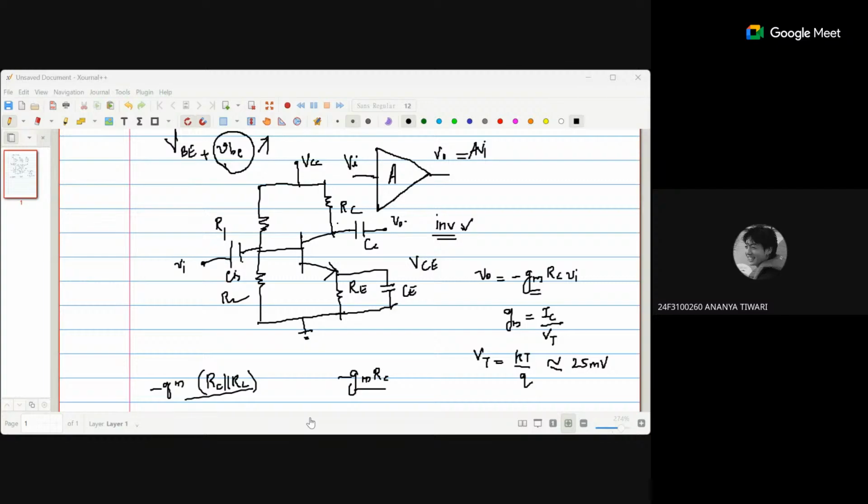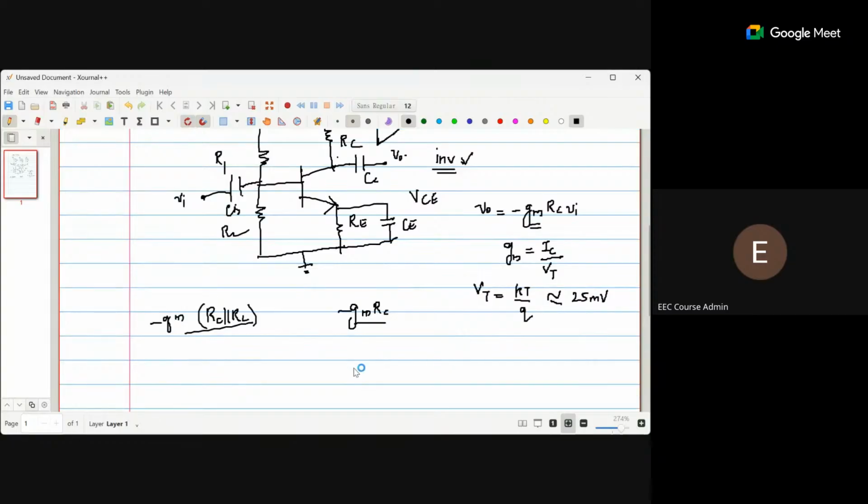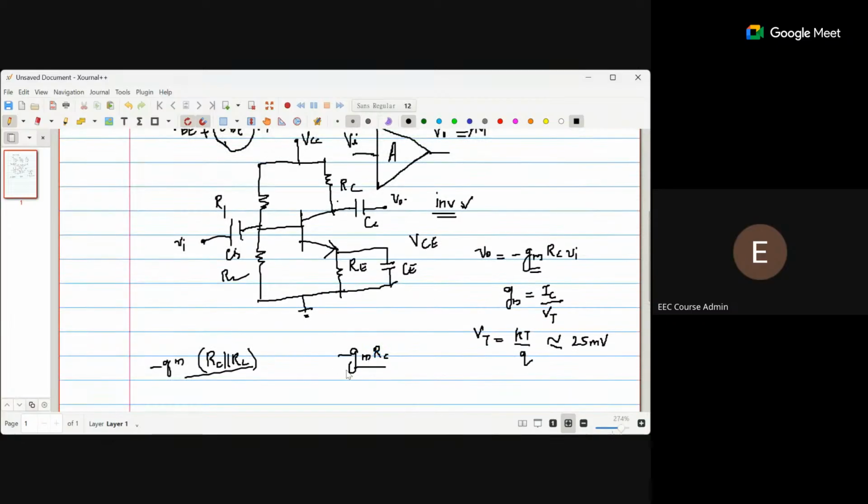So can you repeat it again? Oh, no, he was asking with reference to an assignment question where you have the case of load resistance also, asking for the small signal gain. We are talking about the small signal gain. That means only the signal part we want. So we are setting the DC to be 0. That means I set this VCC to be equal to 0.